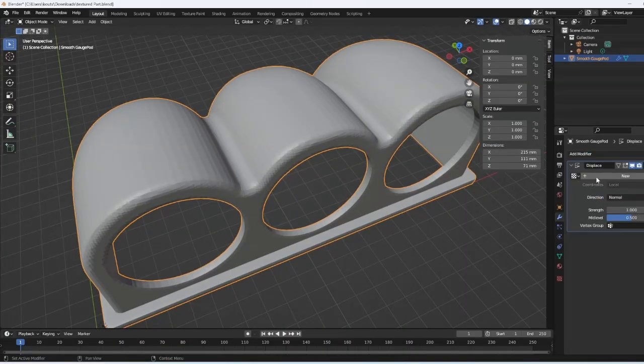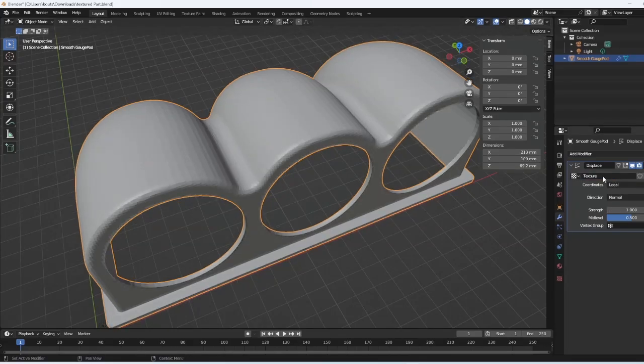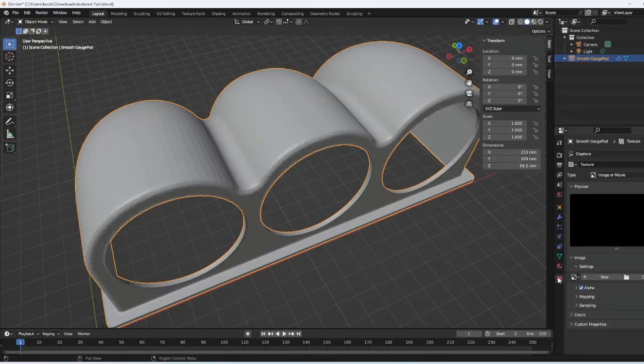So we have to actually add the texture. There's no textures that we've added. Once you do this once, if you open another part up, the texture will be there, but the first time you've got to hit new texture, and we haven't actually given it the image of this texture yet. So we have to go to this part here, show texture in texture tab. Now that's actually down here. You can see texture, but if I click on this button, it'll just take me there.